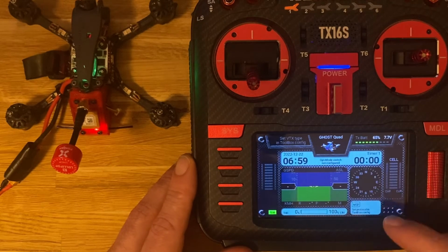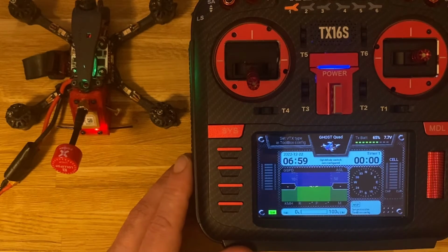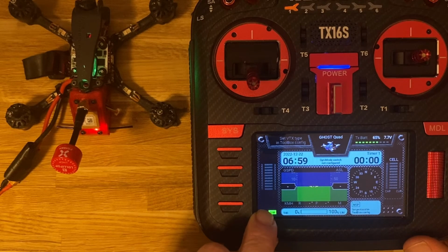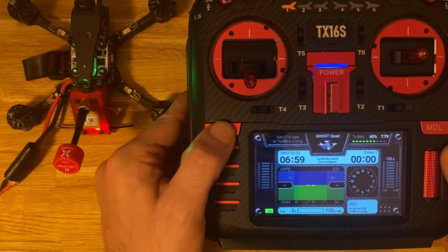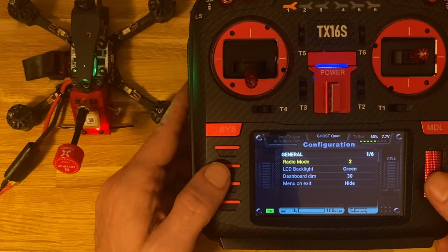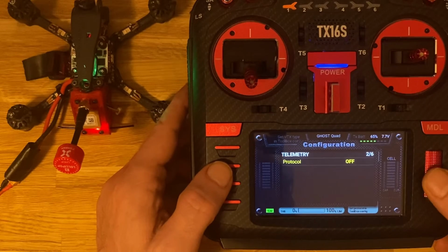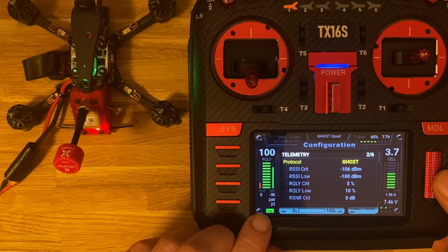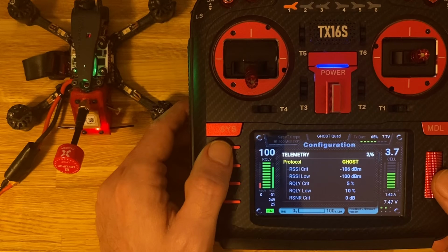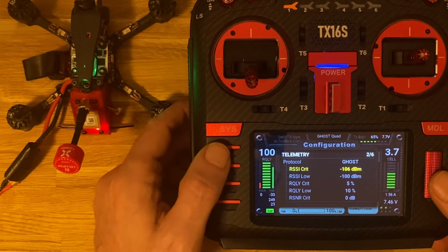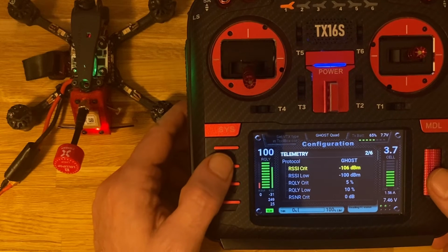Gyro mode switch is not configured, MSP protocol is not configured, and RC link is not configured because you cannot see icon of telemetry protocol, RC link protocol, sorry. So let's go to configuration and quickly configure Ghost. Now it's set and you can see values. Oh, I can see no icon showing. This will be fixed in RC3, small bug.